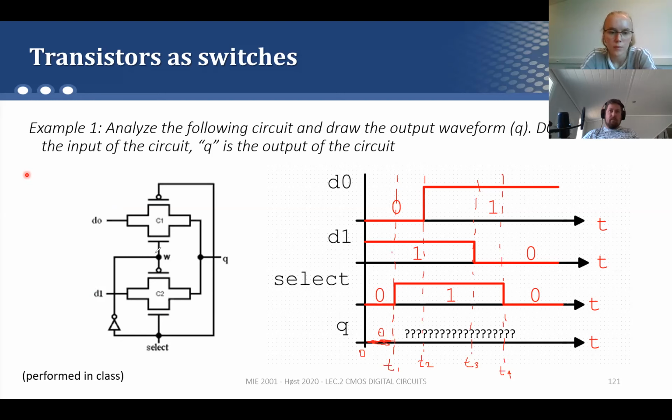You can see in the circuit here, there is some black dot where it crosses some wire, but here there is no dot. So what does this mean? It just means that this wire goes over the other one. This one is electrically connected together, but here there is no electrical connection. It's just because the drawing cannot be done in another way. I mean, it can be done in another way, but I can show you how it can be drawn.